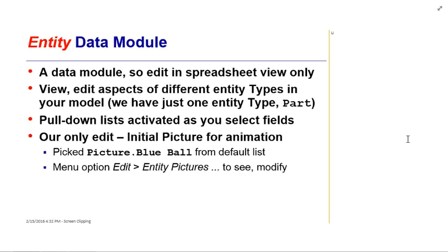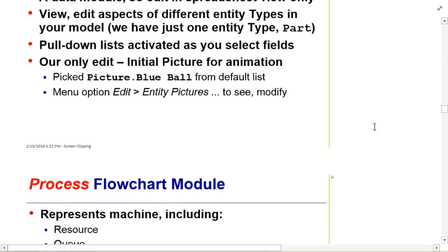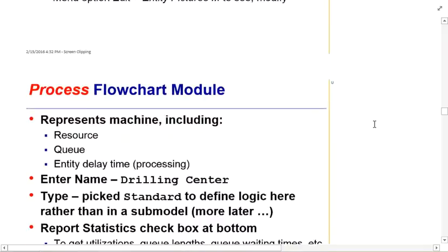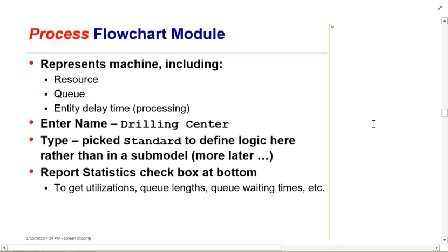You can see a queue where, say, my normal condition is all blue balls, and my higher priority is a red ball. When that entity comes up into that process, you'll see that red ball shoot right up to the front of the queue. It's a useful visual to see what is really happening, but again, it doesn't affect the simulation. It's just useful when you're trying to debug something or make sure what's happening is really what you want to happen.